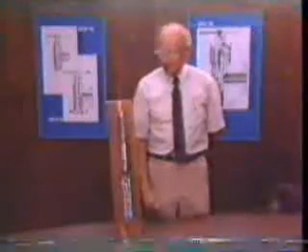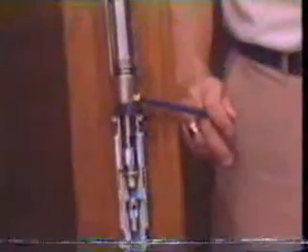Let's join Ed DeMoss of Teledyne Merla in Dallas and have him show us a good cutaway of a pressure-operated valve. We have here a full-scale pressure-charged gasless valve, 1.5-inch size that is wireline retrievable. The various parts of this valve are the dome, the bellows, the packing, upper packing, which separates casing from tubing, the ball or stem, the seat, the back check, and the lower packing.